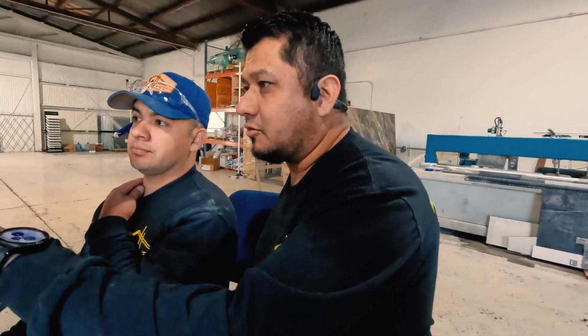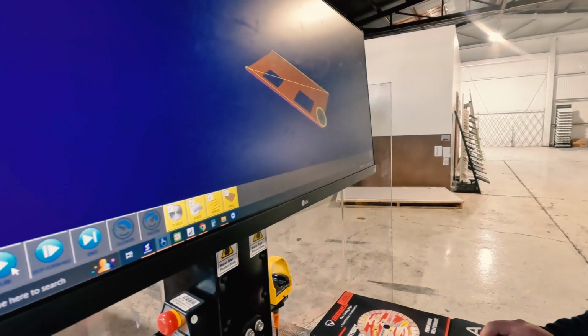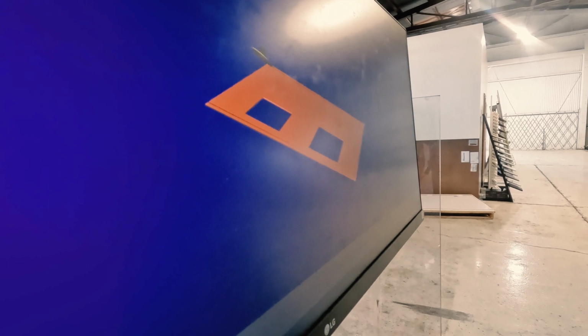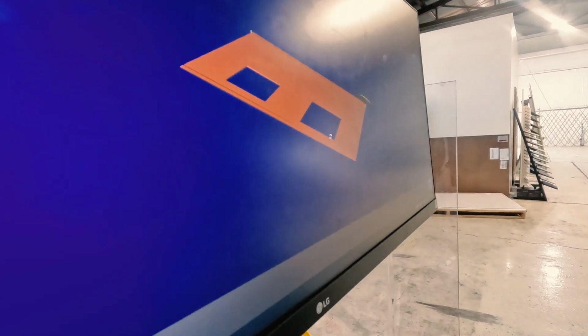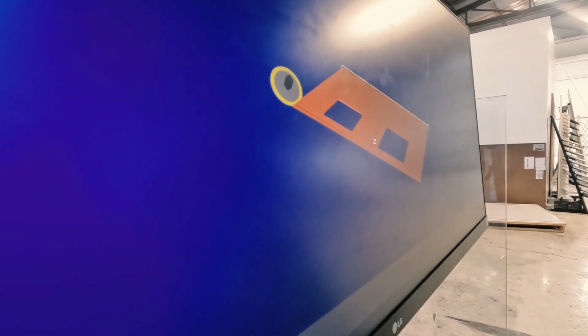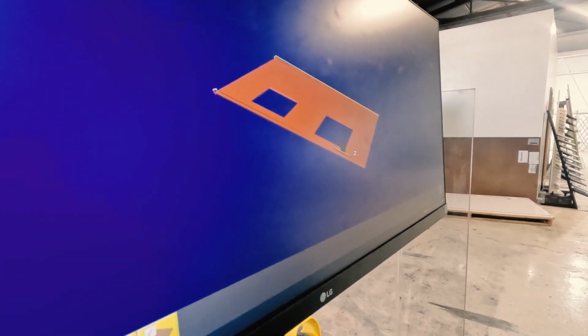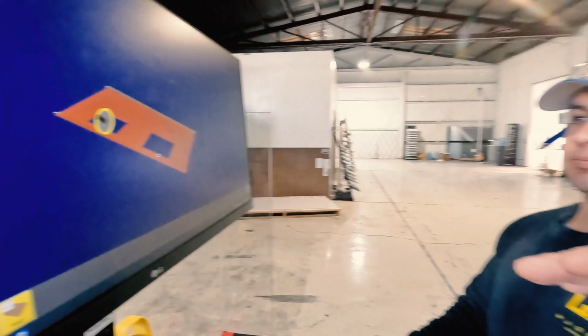Okay, so right now we have all the cuts figured out. What we're going to do is send it to simulation, and you're going to see how the blade moves just to make sure we are safe on all aspects. So you see how that's going? Basically, no surprises for the operator. You want to know how it's going to happen. We definitely want to make sure our miters are one in and one out, so we don't have any miscuts.